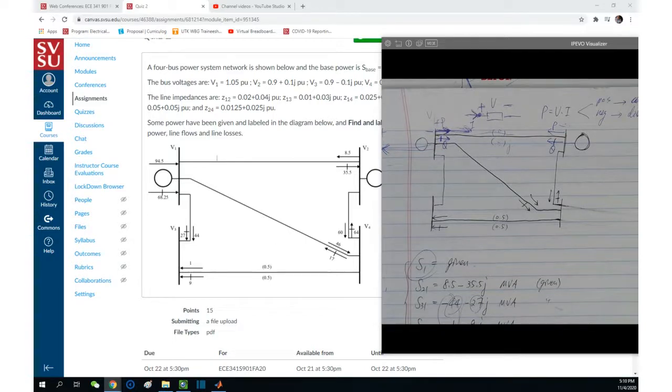Capacitor bank is considered as load. Yep, another bus containing a load, which is capacitor bank, trying to compensate the inductive of the line, of another load, because generally speaking, the load is inductive. You use capacitor bank to compensate that load.